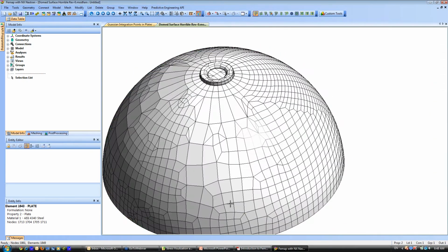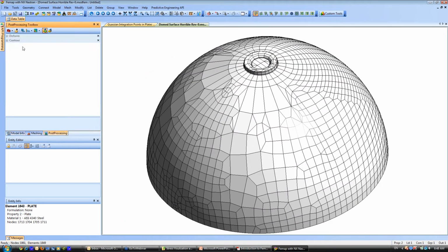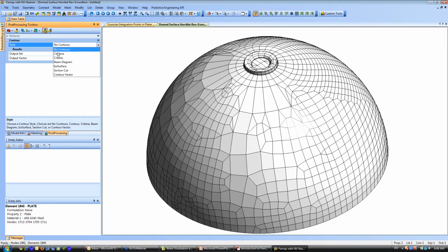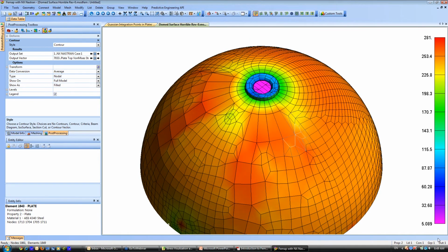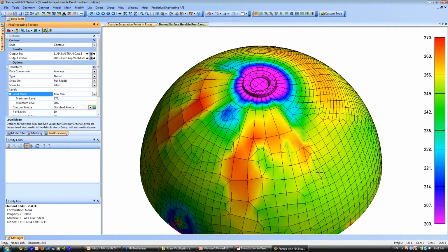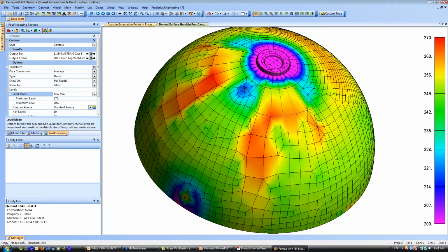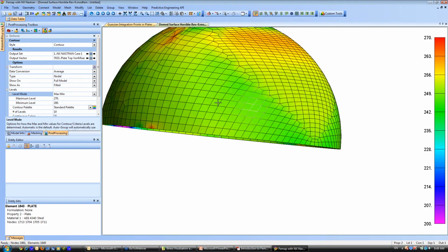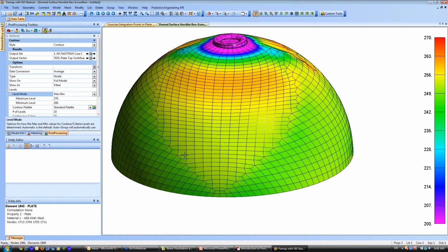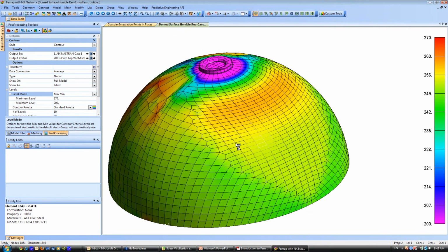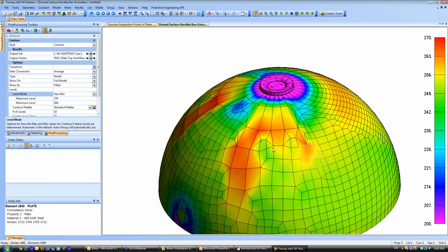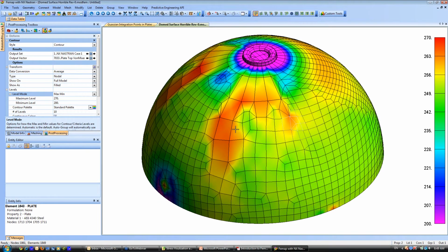So, but let's turn that off. And I just threw some stresses on it. And we can go into post-processing and contour. And we can say contour right there, like that. And now the legend is scaling from 5 to 280. And what we would like to do is go into levels, and let's not do auto. Let's do max min, like that. So I've already bracketed it from 200. And now you can see the problem jumps out, that that is bogus. That's not correct. That can't exist. And you look over here, and you go, that's the way it should look. Beautiful, smooth, continuous. It looks good. It's pleasing. You look here, you just, how would you say, you don't need a Jacobian to tell you it's cooked.